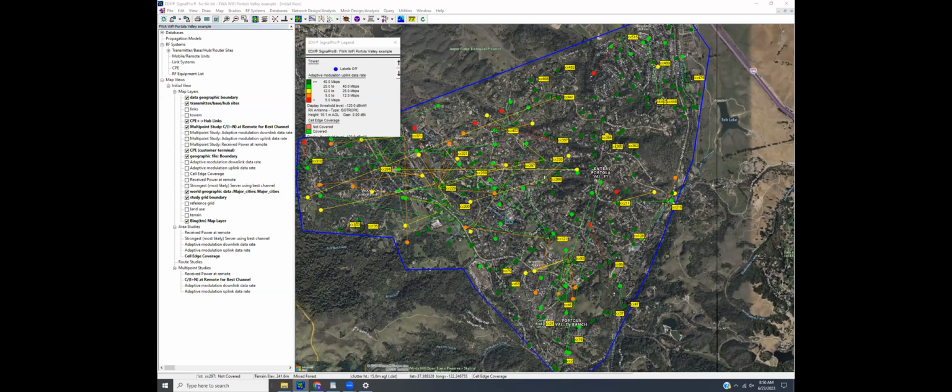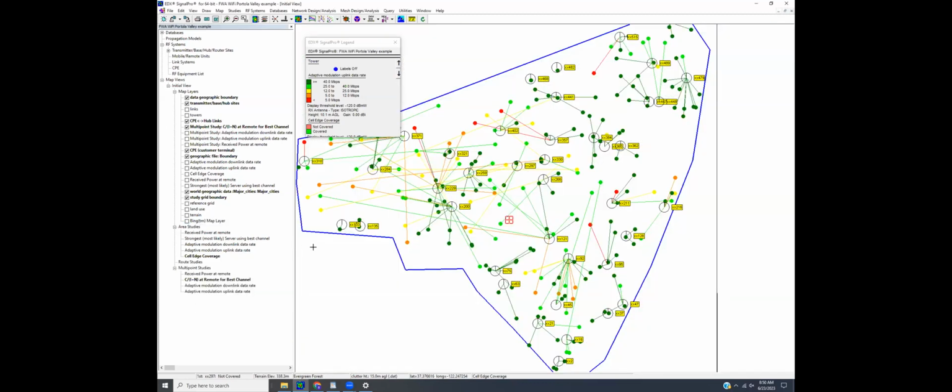Oh, there's one last question here, whether the green link lines are reliable or desirable to show on a map. As far as the display settings here, I displayed mine where the dark green is the good color, and, here, let me hide my Bing map, going toward red being the bad colors, red and orange, and all of that's completely user configurable. If you want to set up these displays to use a different scheme or change how the link lines are displayed, you can do all of that.